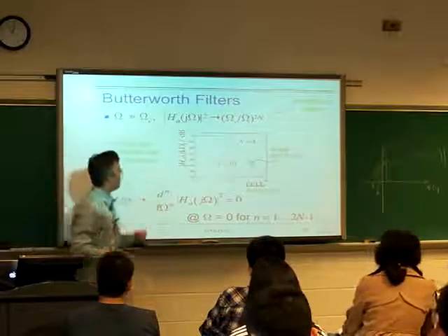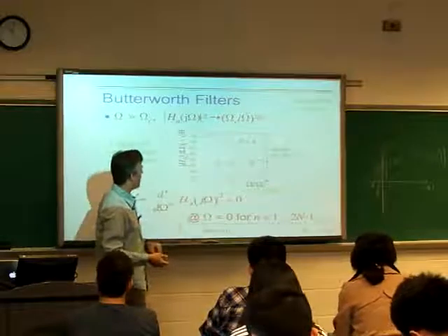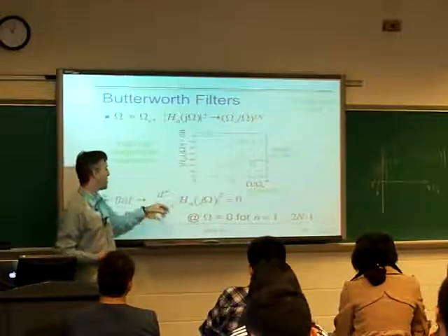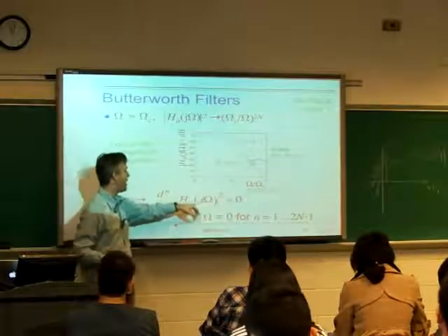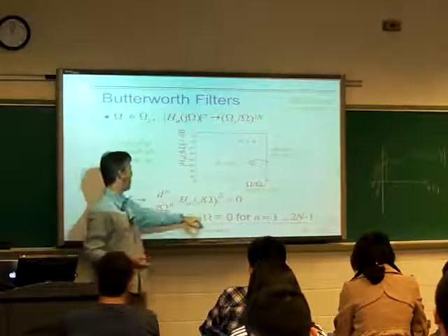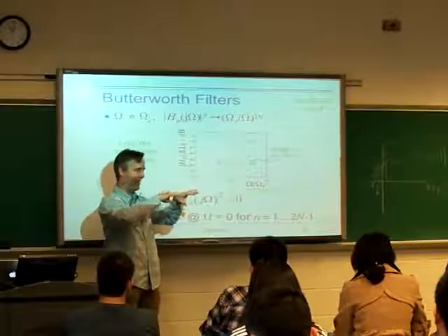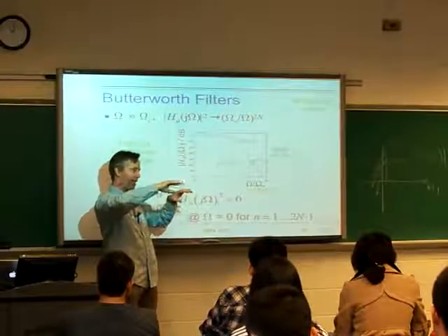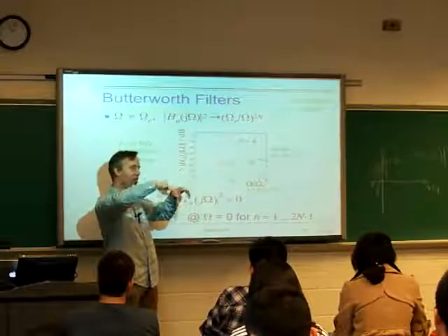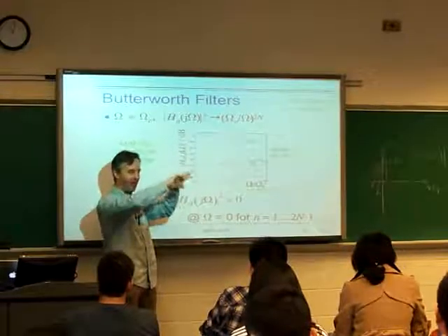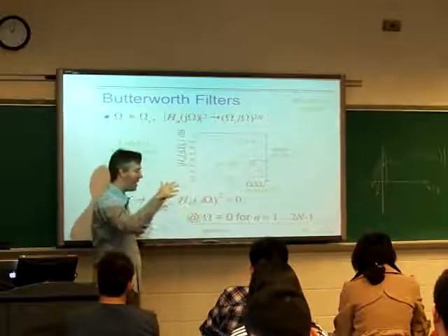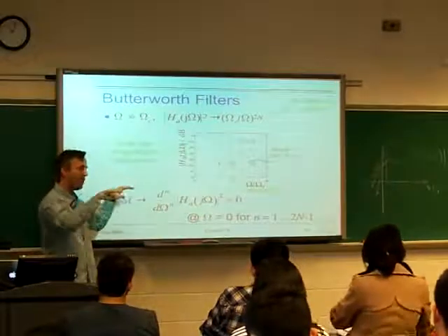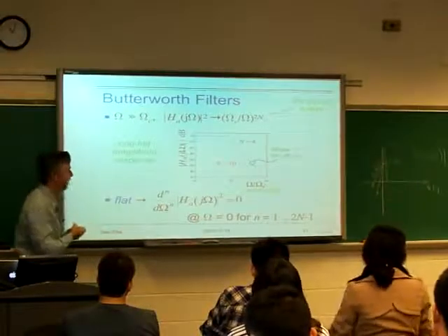Okay, so that's our log-log response. I mentioned the definition of flatness is actually that the nth derivative at 0 is 0. So it just means that before you can even get some slope, you have to get the curvature to be non-zero, and then the derivative of curvature, the rate of change of curvature of the frequency, has to be non-zero. So if you set our derivatives to 0 at a point, then the flatness extends out further.